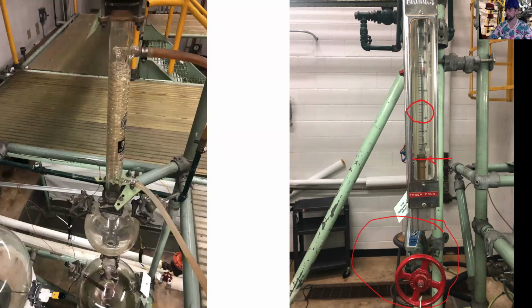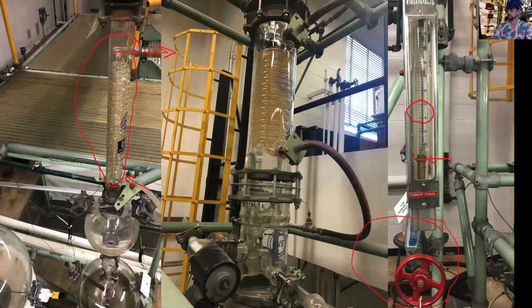And so the condenser, you can see closest, is right above the final collection bin. You have a little tiny one here, and there's a few valves that turn it. You can see it flowing in and flowing out. Be careful not to turn it up too fast, because there's going to be some air in there that you want to take out. And here's the larger condenser unit at the top of the column. You have it here flowing in and flowing out.